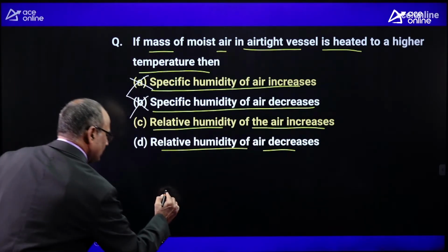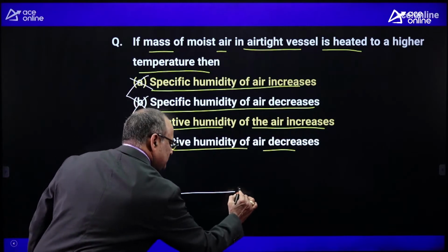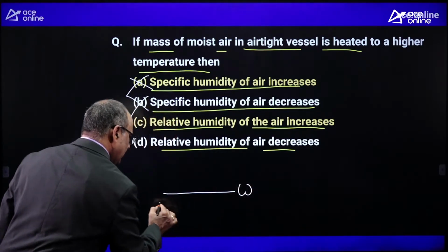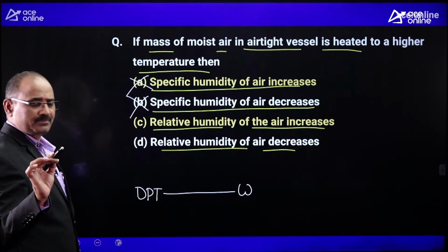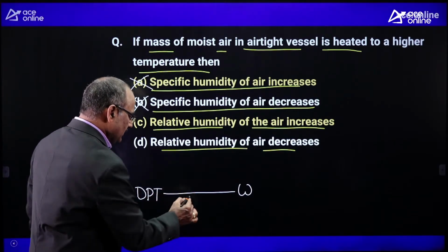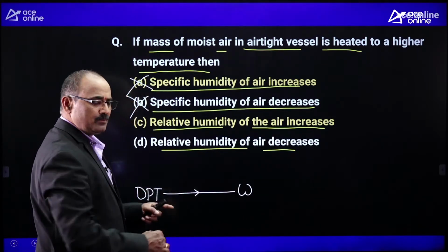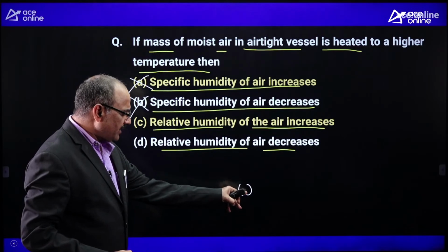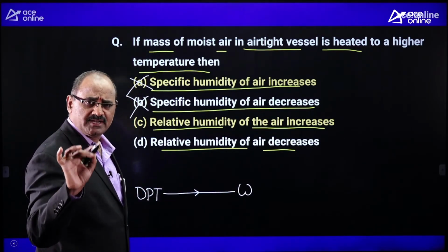The horizontal line in the psychrometric chart is giving specific humidity at its right end and dew point temperature at the left end. From that I can say that during the sensible heating process and sensible cooling process, not only specific humidity is constant, but also dew point temperature remains constant.